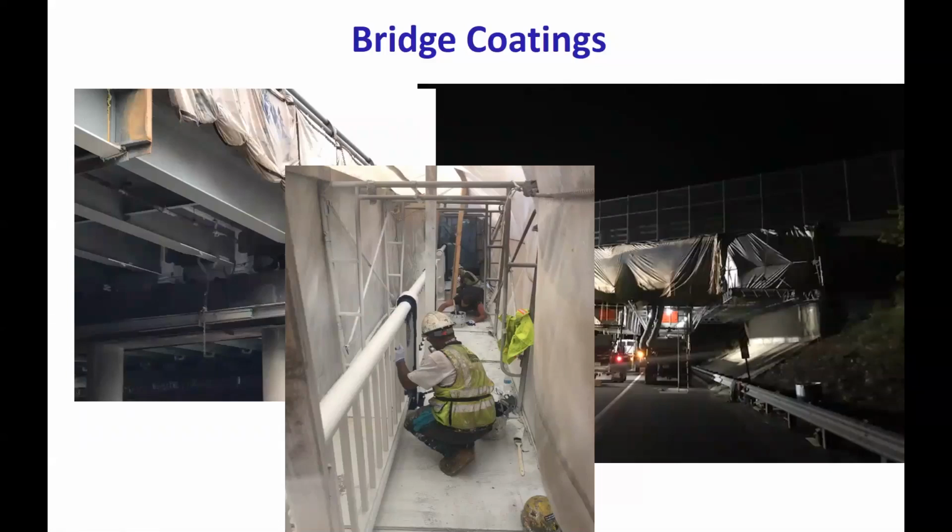Also, because of the requirements for technical specifications, most of these paintings require a minimum temperature and a certain relative humidity, which shouldn't be very high because then it would compete with the polymerization chemistry and the quality of the paint. So oftentimes in these containments, one would end up with environments that are both hot and humid, but not condensing.